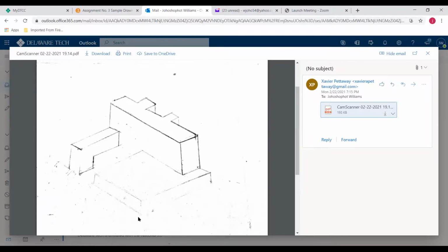This line is right, but this line, you need to erase out and start from this point right here, keeping this line 30 degrees from the y-axis, and draw it so that it's 2 feet here and it's 2 feet here. You say that's the right one, but the height here is different because the angle is different. So go ahead and make that correction.